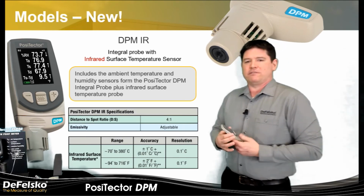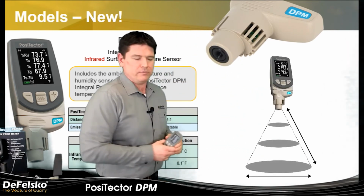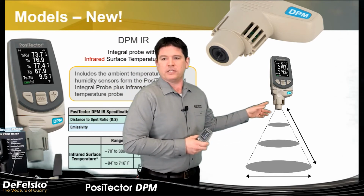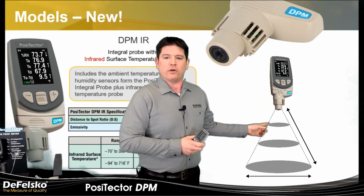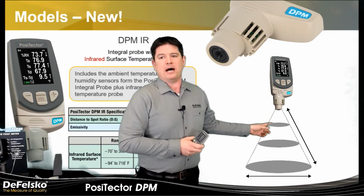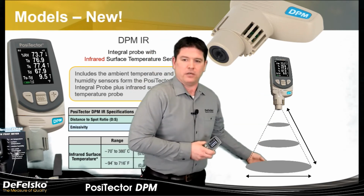It has a 4-to-1 distance to spot ratio, and we'll pull up a little graphic here to show you what this means. So the distance to spot ratio refers to how far above the surface the gauge is versus how much of an area it's measuring. So when I'm 4 inches off the surface, I'm measuring a 1-inch spot. 8 inches up, I'm measuring a 2-inch spot. 12 inches, a 3-inch spot.